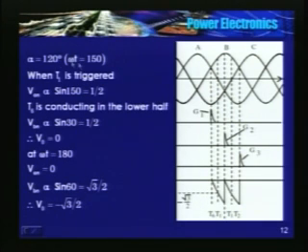So for alpha is equal to 120 degrees, if I summarize, it becomes 0 and always negative. Whatever happened for alpha is equal to 60 degrees, we found that the instantaneous or minimum value of V naught is 0 and it is positive. Okay. So at alpha is equal to 120 degrees, it is 0 and negative. Just the opposite. These are the two pulses.